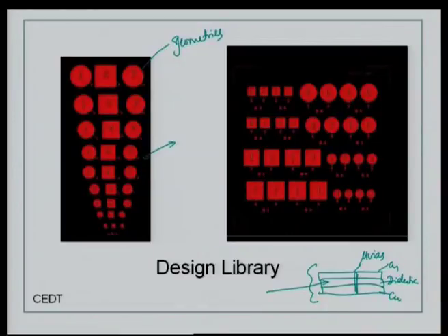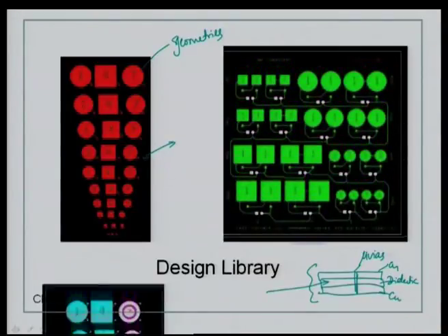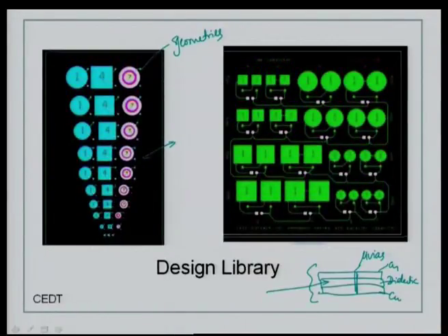Then in the build up you will have a dielectric material overlapping these particular structures, and then you will have a foil or added copper to the dielectric material, and these will be interconnected through micro vias for testing. So, these geometries will behave as a capacitor.